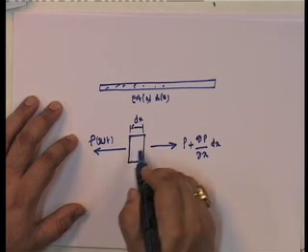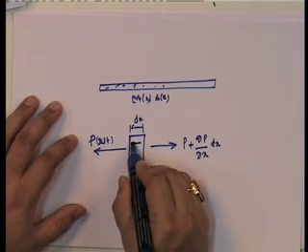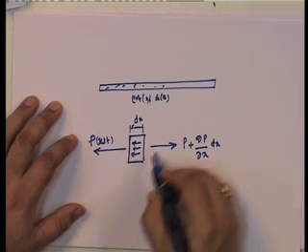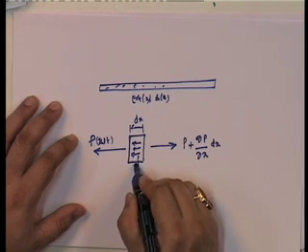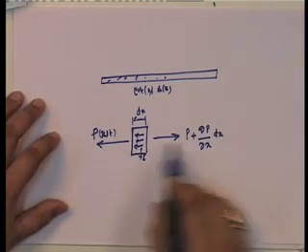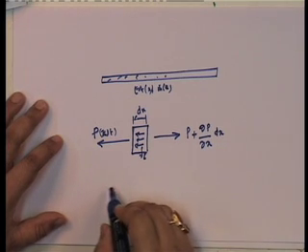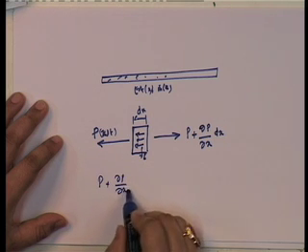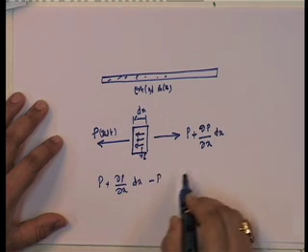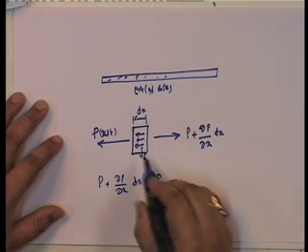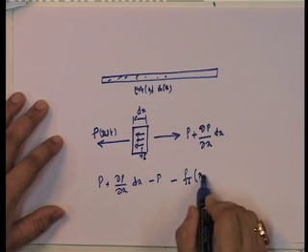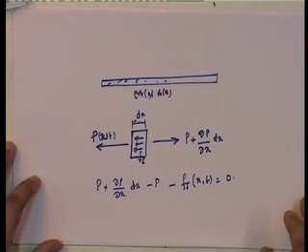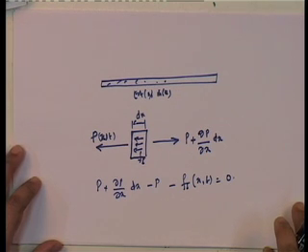These are the forces, and on top of that, you have inertia forces. If I look at the equilibrium of this, I get the following: P plus del P by del x dx minus P minus f I x of t is equal to 0.